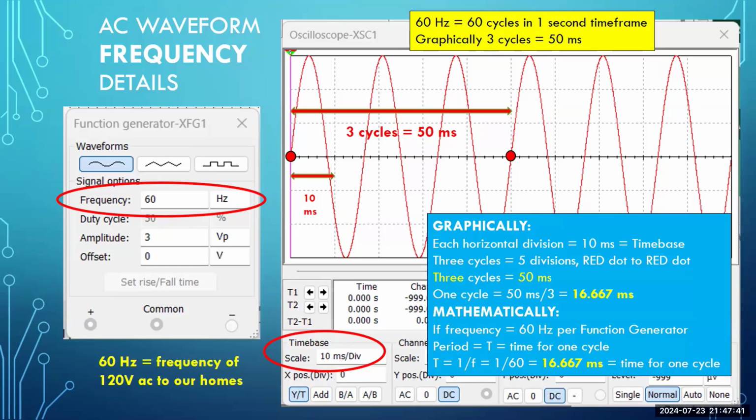It happens to intersect the waveform at the 0 volts reference line, where the value of the waveform is also 0, meaning it's the crossover between the positive half cycle and the negative half cycle. And they happen to intersect the 0 volts reference line as well as the vertical major division line. This gives you a good opportunity to count the number of cycles between those divisions.